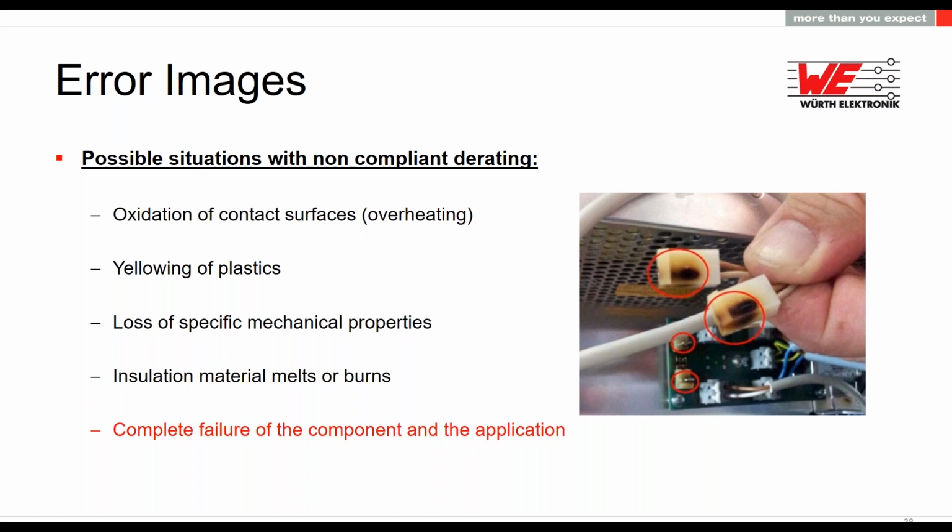But if you think about designing a street light, in winter it has -15, -20 degrees at night. In summer, it has +65 degrees in the housing, in the sunlight. So your connector has to carry all that. And of course, this is what limits then the current you can apply. And if you don't respect it well, you can really have issues with that.